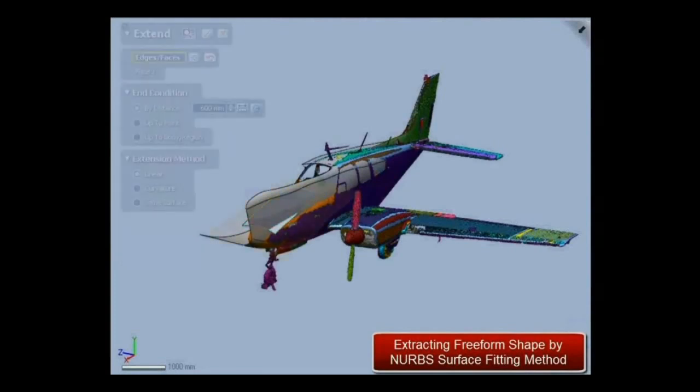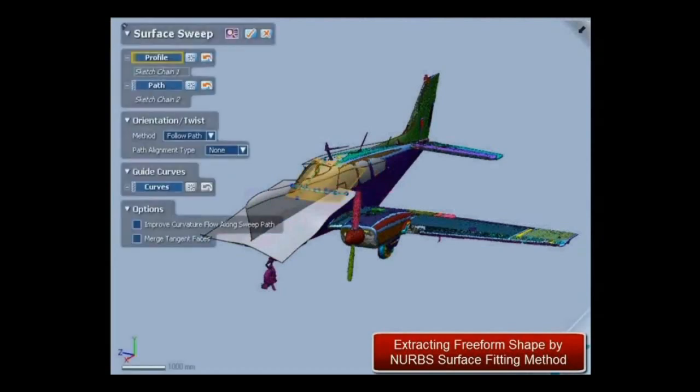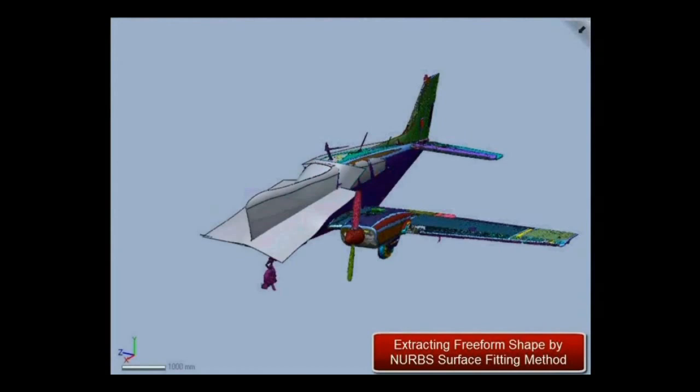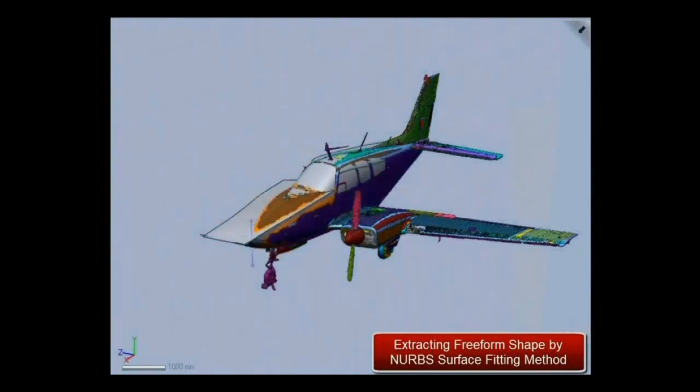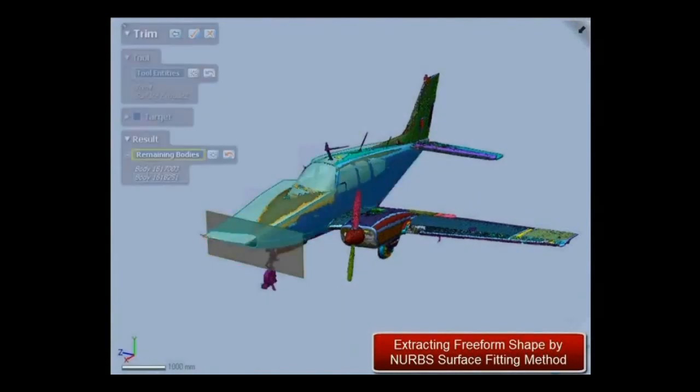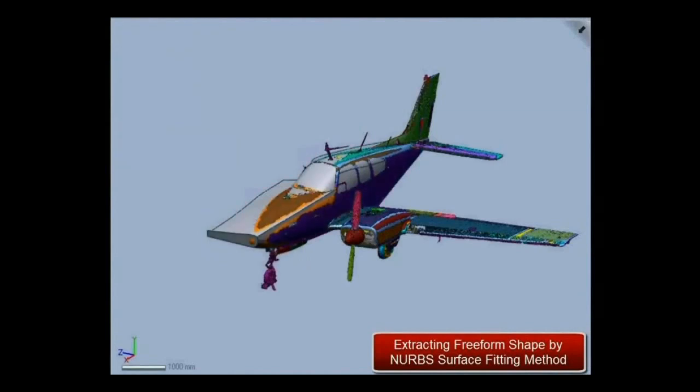And the loft wizard also supports us with two methods based on accuracy. That means based on a maximum allowed tolerance to the mesh, or based on number of sections. And after the number of sections selection, we can also see a preview.